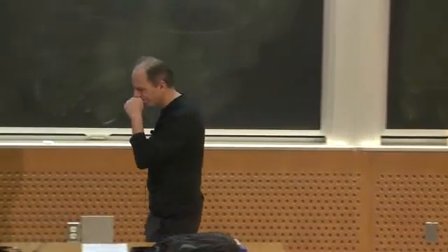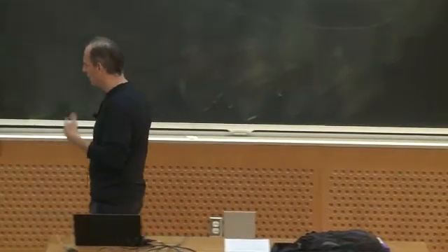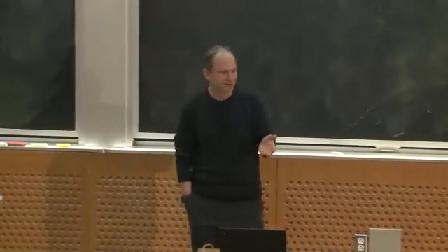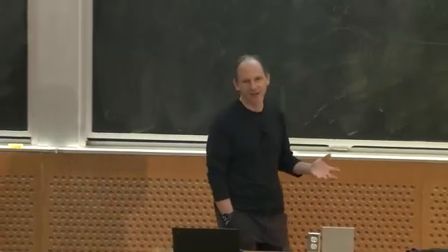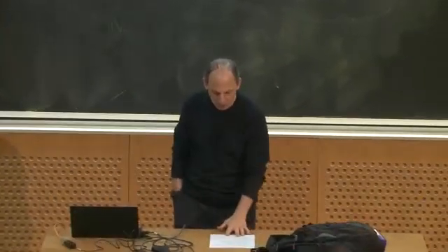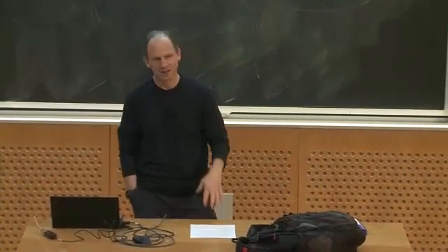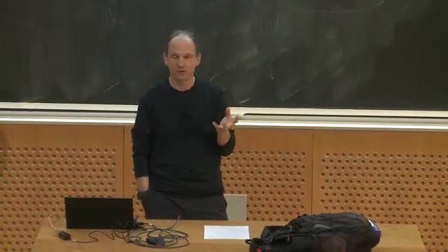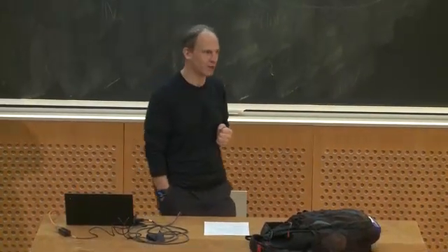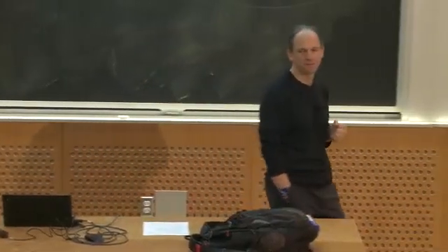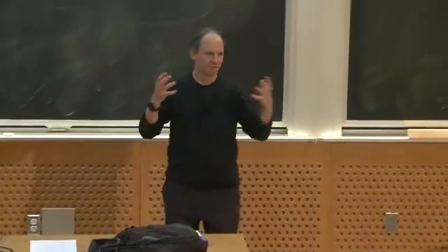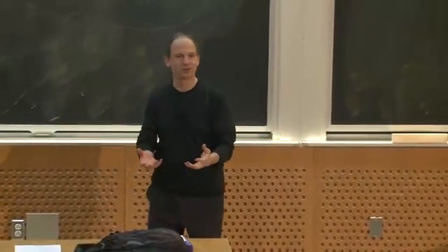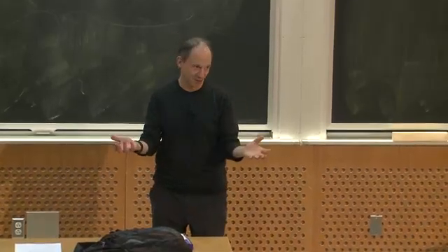Okay? So, if I'm going to design a magnetic component, I really have to think about loss. And loss is important for two reasons. If you have bad magnetic components, the magnetic components tend to be the dominant source of loss in a converter for the most part. So in a typical design, if you don't do a good job on the magnetics, your efficiency is going to stink.